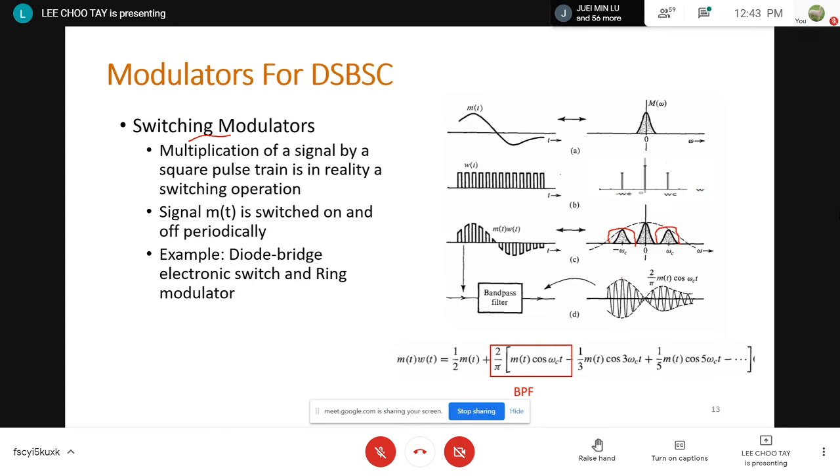If you look at the signal itself, the carrier now has the high frequency. We have a series of high frequency signals at the carrier frequency, and the amplitude of the carrier at different times follows the amplitude of the message here. You can see that the envelope follows. What we get rid of is the high frequency component at the sharp transition here. The frequency is too high for the system to respond, and we don't want this high frequency. We want to transmit our signal at omega c only.